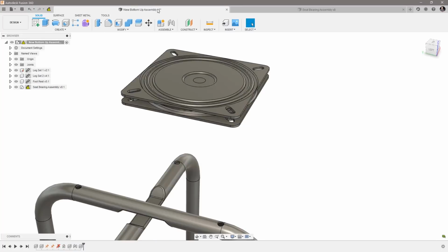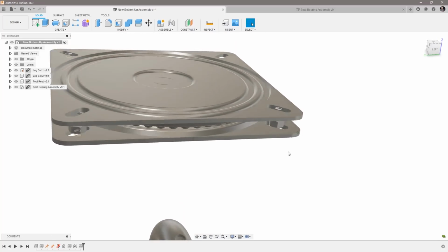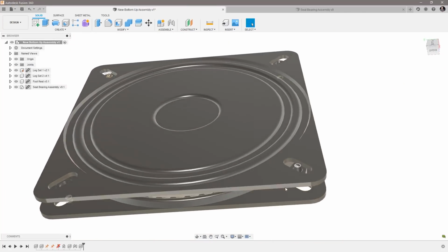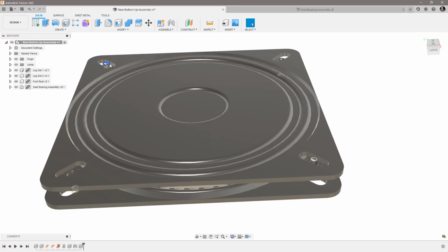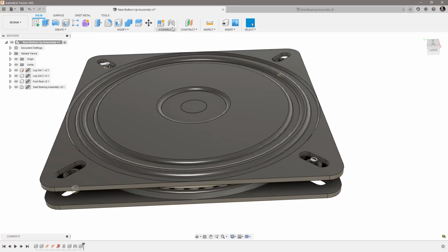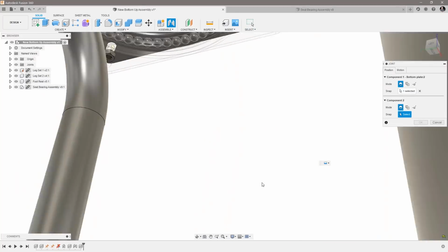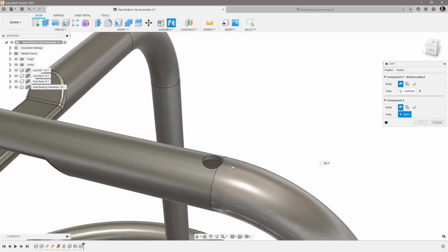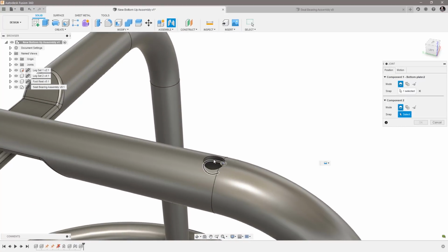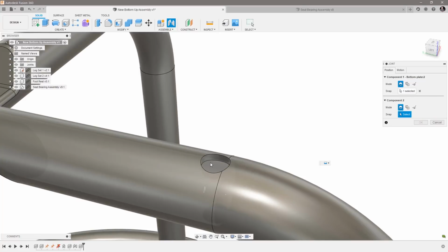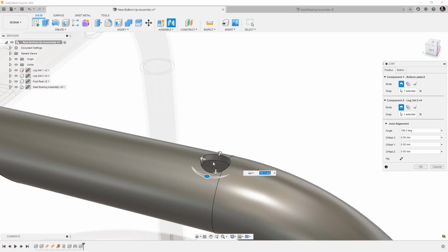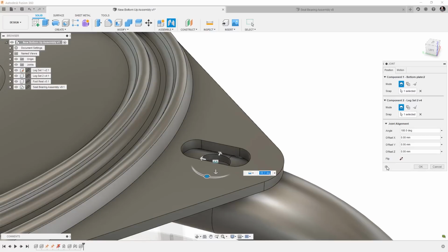Now if I go into our assembly, I actually get an update because we deleted and we saved. So I'm going to hit that. It's going to update everything. And now you can actually see those joint origins appearing there and there. That was who we created. So now I can go in and say joint, and now I can select those. Joint origin there. Let's find the top of this one. Right. Zoom in. Whoops. Right there. And that goes into place there.